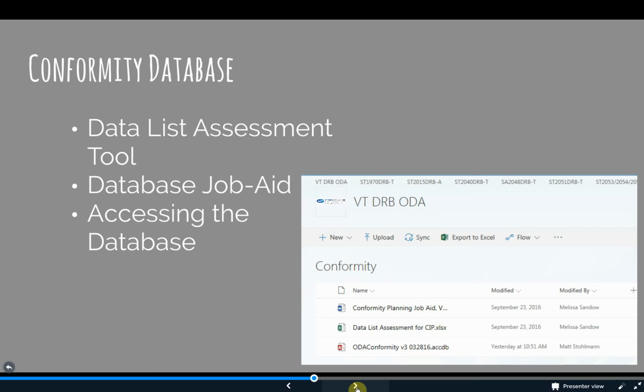Items that have been previously approved, such as through a PMA, TSO, or earlier STC, do not need to be conformed again, nor do items that do not contribute significantly to form, fit, or function. If a part or assembly will affect a test or evaluation, it needs to be conformed. When making an assessment, the ODA is interested in special processes used, new vendors, and unique design features. These should be included in the proposal for what is and is not conformed by the ODA.